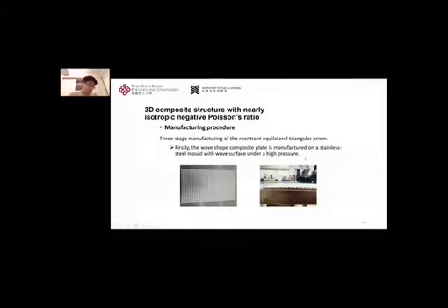But as you may know, the carbon fiber has a very high modulus, which makes it quite difficult to bend to fit this reentrant triangle mold directly. Another problem is that even when we force it to fit this mold, it's quite difficult to demold after the curing. So in our process, we use a 3-stage method, which is quite silly, stupid, but it's useful. It's working for making this kind of composite.